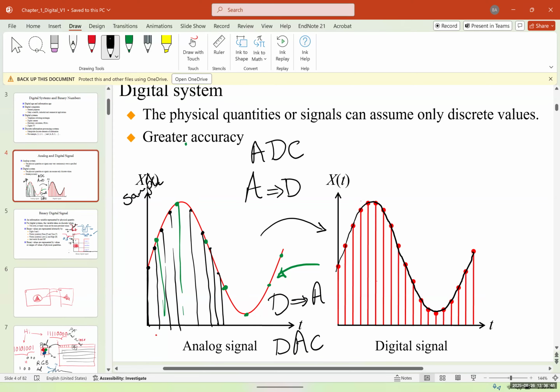Now let's go to the hardware part. What circuit do we use? If we have an analog signal, we can simply use a switch. And from that switch, this is V out. You can have a load or not. So this is your analog signal, and you have a switch that is switching at a very fast rate. I'm going to show it with just S because I don't have space to write it all. Depending on the frequency, if you want to do it 10 times per second or 100 times per second, you just close and open the switch, okay? So sampling is as easy as that.